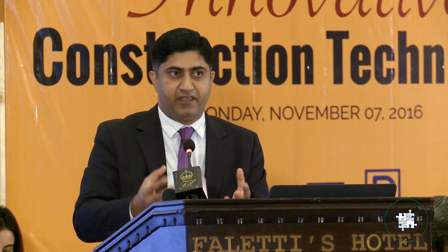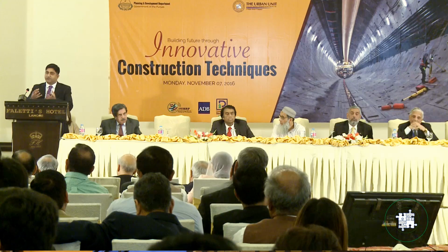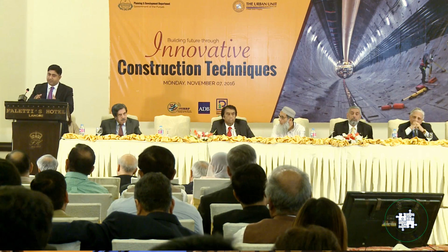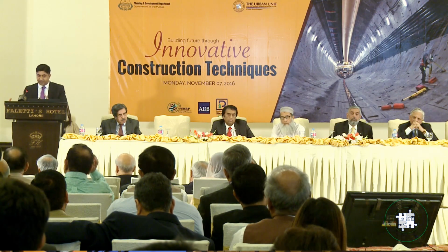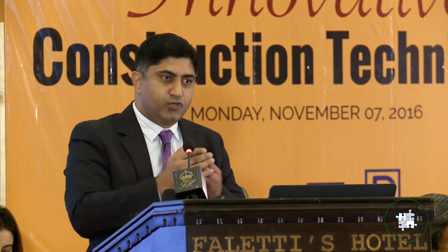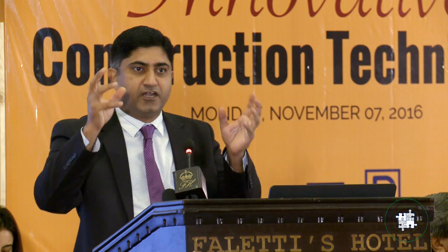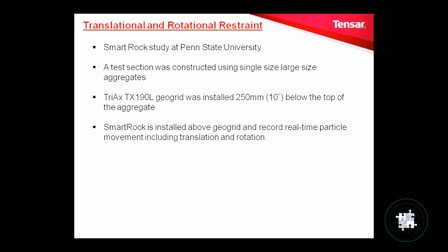So what we need, if we have a product at the base of this unbound material that restricts this tension ring and reacts against the tension ring, we can get better performance. I'll show you one more piece of research work that will show you the rotational kind of movement that happens in the aggregate layer.